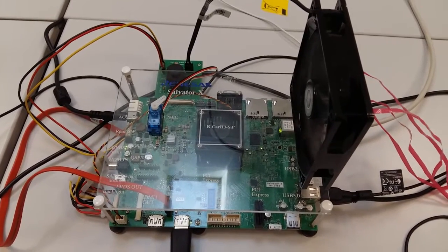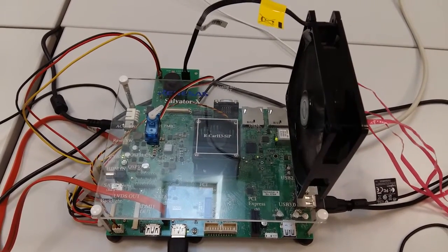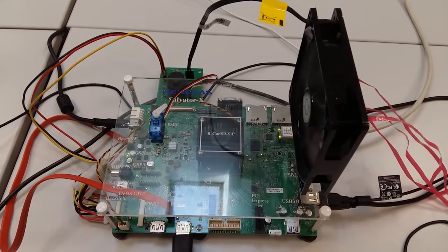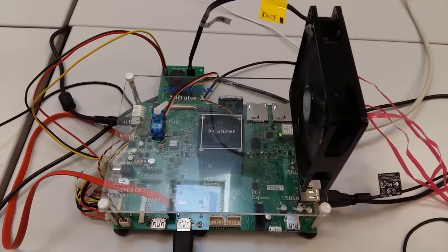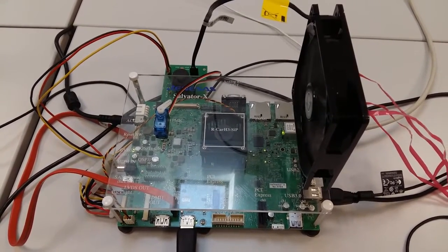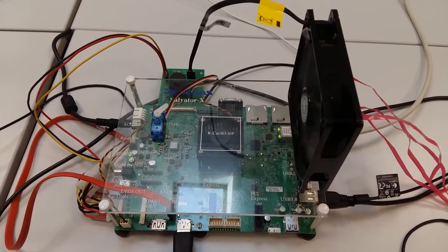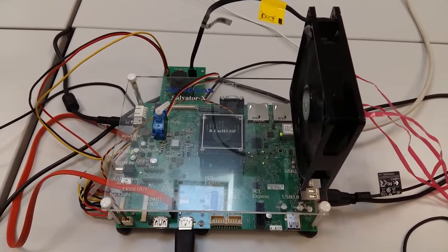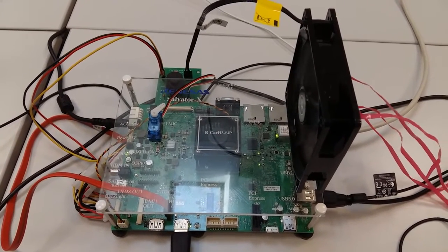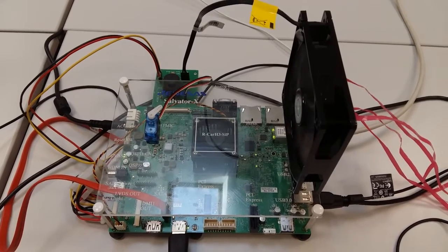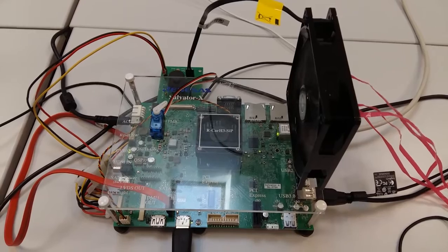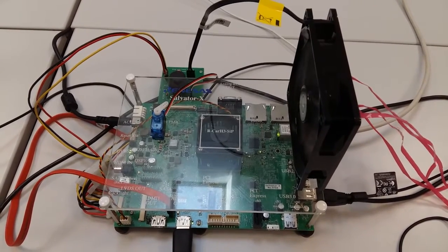Hello everyone, I'm Kevin Chapuis from Virtual Open System, and I will showcase the VOSYSmonitor running on a RCAR H3 board, a platform based on ARMv8 architecture with a quad-core Cortex A57 and a quad-core Cortex A53. So VOSYSmonitor enables the co-execution on the same platform of a safety critical real-time operating system, along with a general purpose operating system with virtualization features such as Linux KVM.